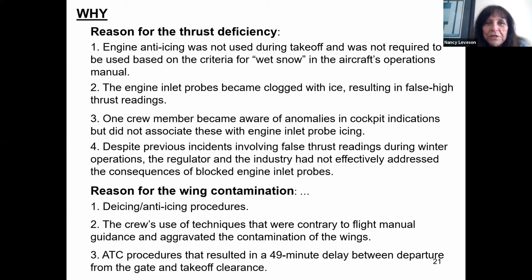What about the procedures? Second, the engine inlet probes became clogged with ice, resulting in false high thrust readings. One crew member became aware of anomalies in cockpit indications, but did not associate these with engine inlet probe icing. All right.